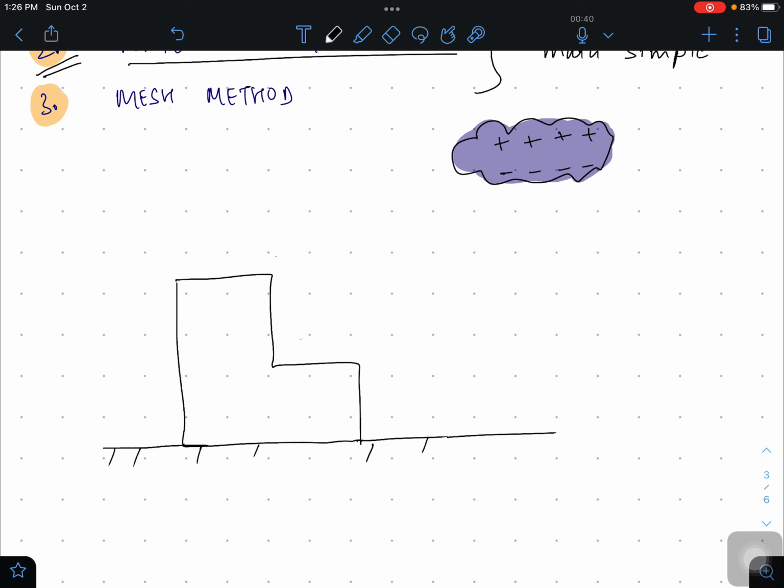So let us suppose there are negative charges here, and due to this negative charge it will induce some positive charge and attract the positive charge from the earth surface in order to ionize this. So now there is a very high electric field between these two surfaces, that is the cloud base and the earth surface. So this negative will try to come down and combine, and this will be seen as a lightning strike. A flow of current then flows.